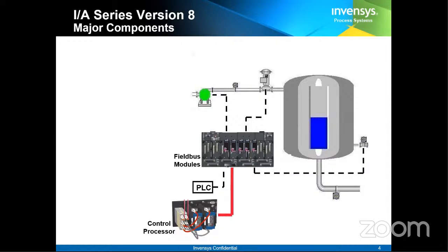As you have mentioned, it has three different control mechanisms: proportional, integral, and derivative. These three control mechanisms work together to ensure optimum performance. The first is proportional control. In proportional control, the action is directly proportional to the error. It means if the error goes high, the output also will go high.